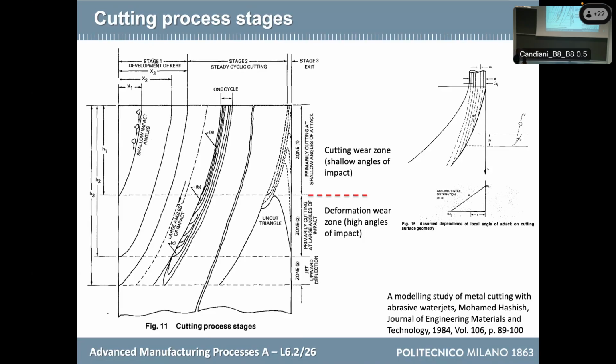A way I have for reducing that wedge is slowing down. What I can do by programming the machine is reducing the feed rate there at the bottom. Because if I do that, the tail of the jet will become almost straight, and so I will remove also this material.